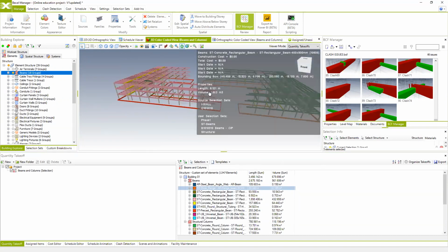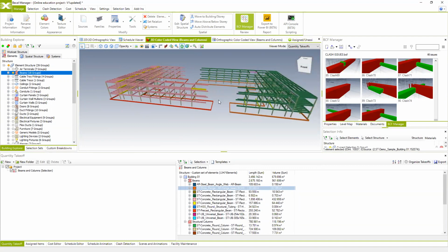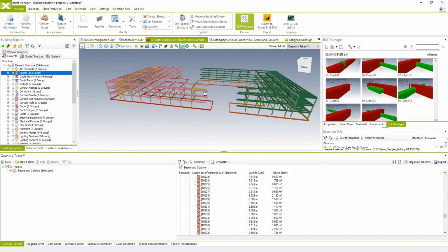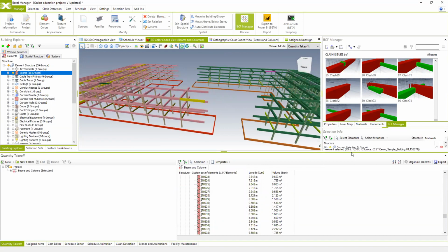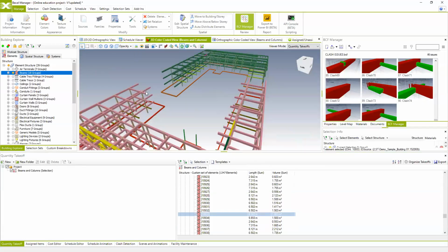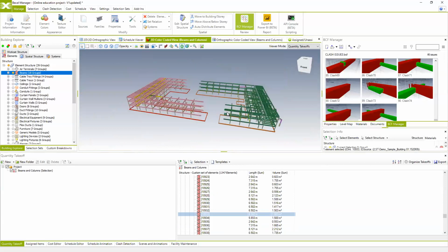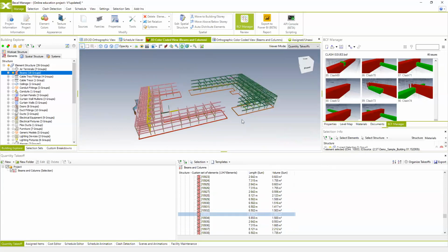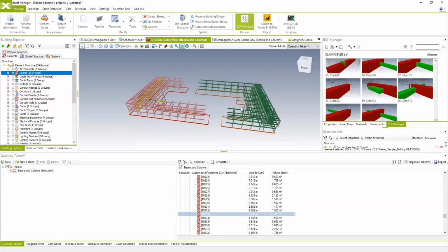Also, it works around if I selected the beam, we can find the elements in Takeoff. So you can see that internal ID for selected beam is 10937. So we can find it right here, 10937. So that's the one. You see it's selected. If I select something else, it's going to be highlighted. So this is the way how you can create your quantity takeoffs from selected elements.